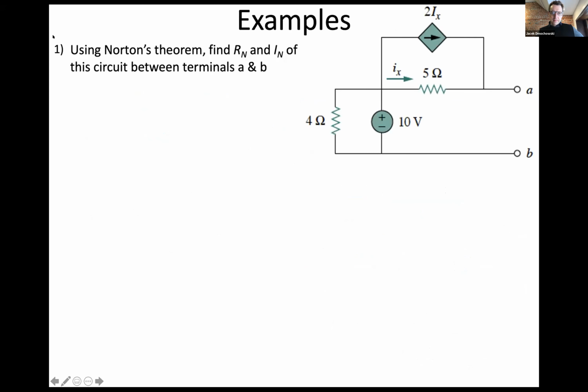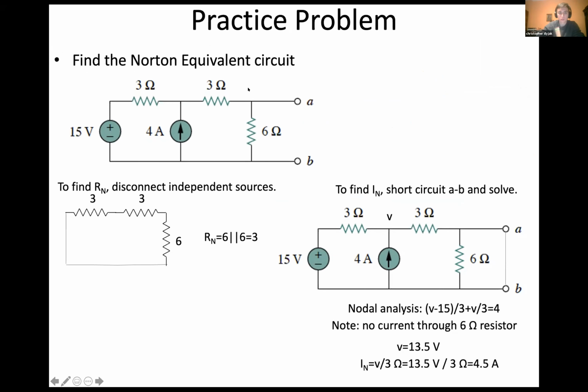Moving right along. So you could assume the bottom wires are ground 0 even if there's no ground symbol. Yeah, that's a good question. So basically, we routinely just omit to draw it, but you can put the ground anywhere in the circuit. And if it's not labeled, you can just assume that it's at the bottom. But yeah, there has to be a reference, because voltage by itself is meaningless. You always need to have a point of reference.